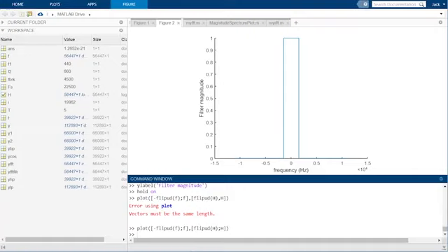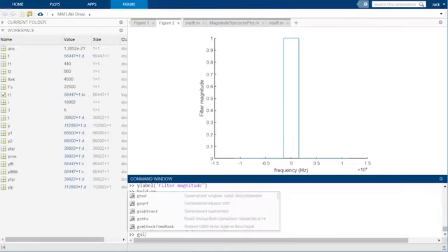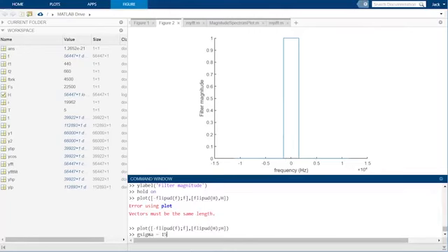Now we can instantly see why this is termed a square wave filter. In the frequency spectrum, it takes the form of a square wave that rises discontinuously to 1 and falls back down to 0 for a specific band of low frequencies less than 1500 hertz. Next, a comparable Gaussian filter. We set the sigma for the Gaussian to be equal to 1500 for 1500 hertz.